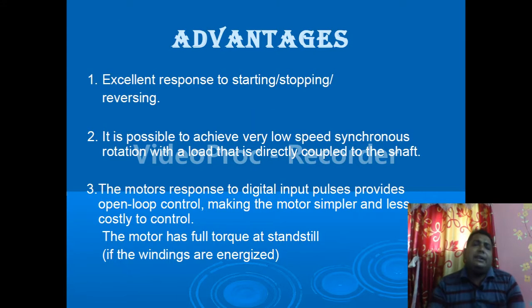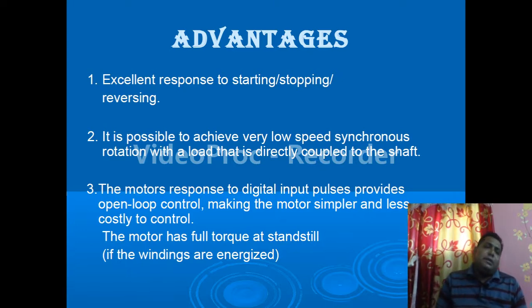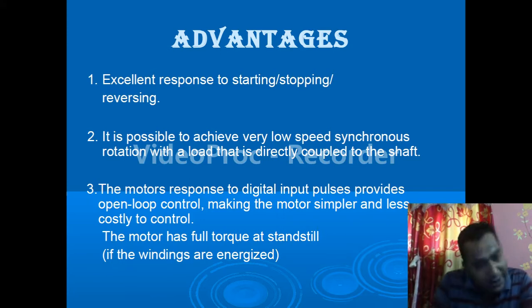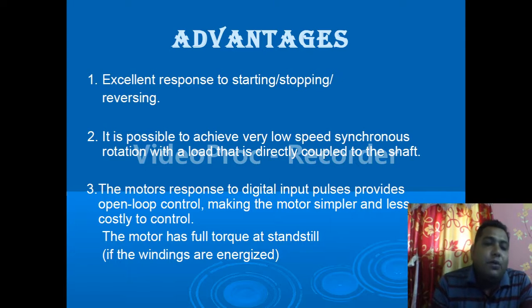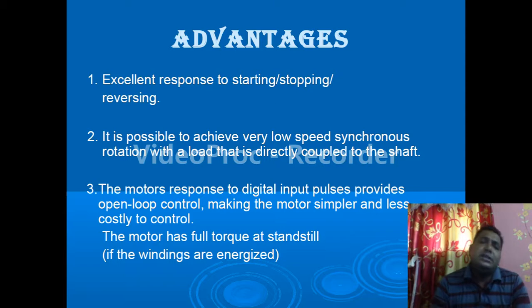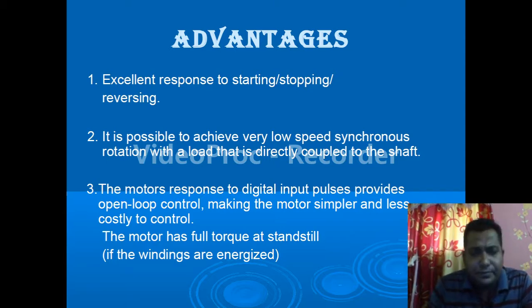Okay, so let us see the advantages. What are the advantages of a stepper motor? Excellent response to starting, stopping and reversing. It is possible to achieve very low speed synchronous rotation with a load that is directly coupled to the shaft. The motor's response to digital input pulses provides open loop control, making the motor simpler and less costly to control. The motor has full torque at standstill. So these are the advantages we have in case of the stepper motor.